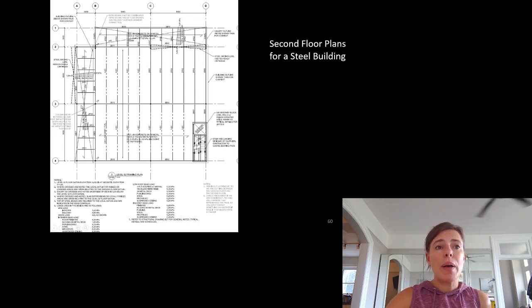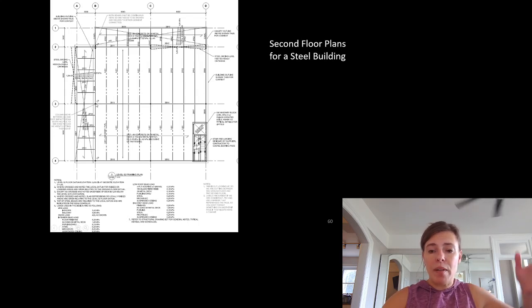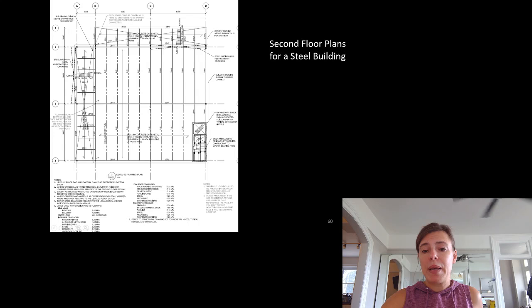CA, this is a column above, so this big beam right here that's spanning from this column to this column has a column up above it, which means it looks like the building is smaller above. This would probably be a girder. We'd call this bad boy a girder because it is picking up purlins and a beam and a transfer column. So it's doing a lot of heavy lifting, and we'd call it a girder.